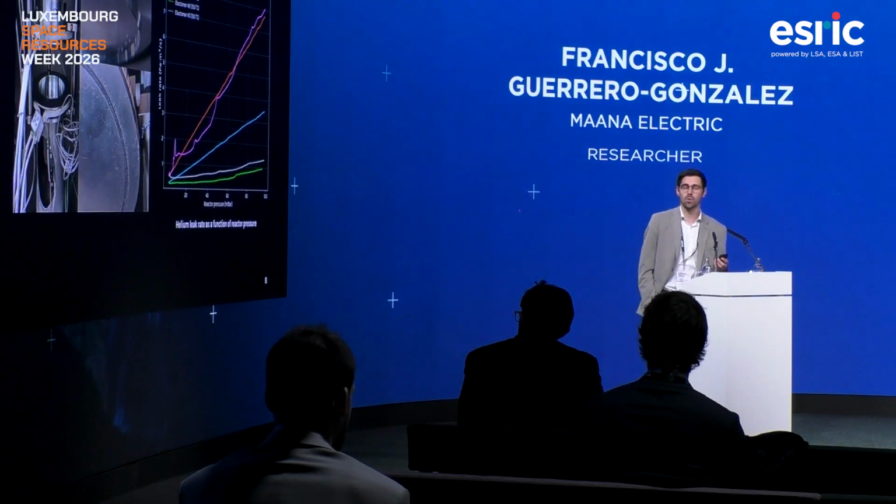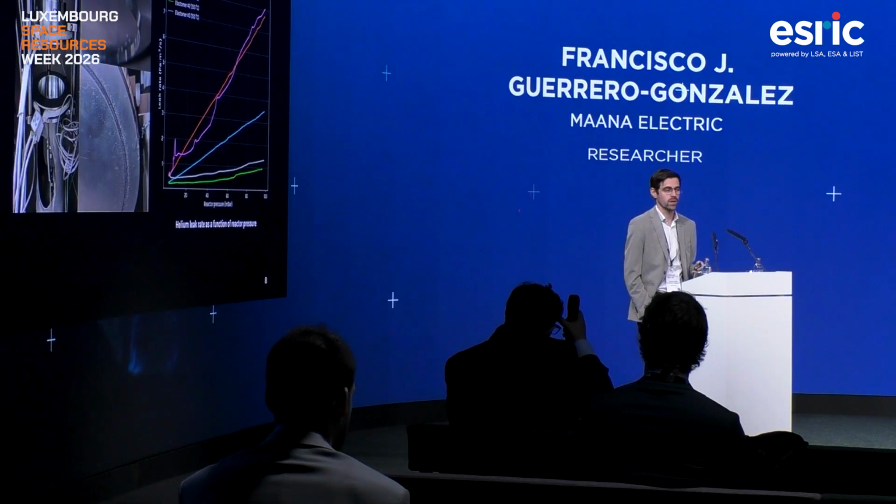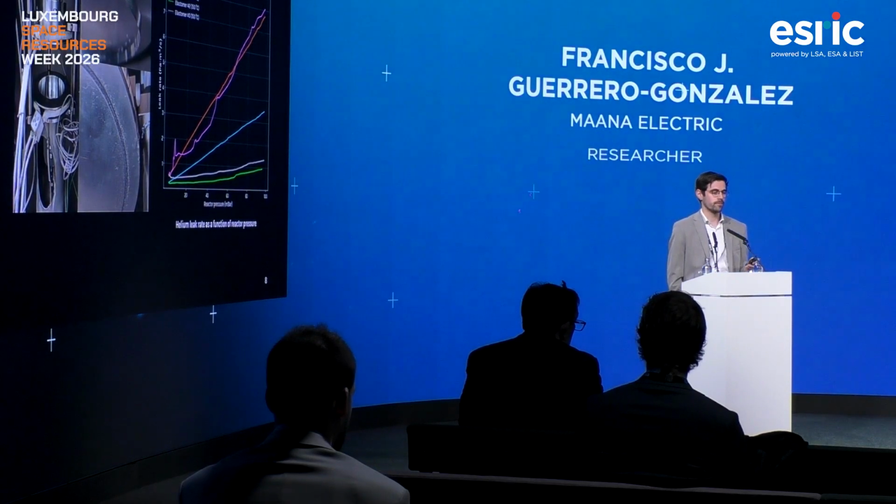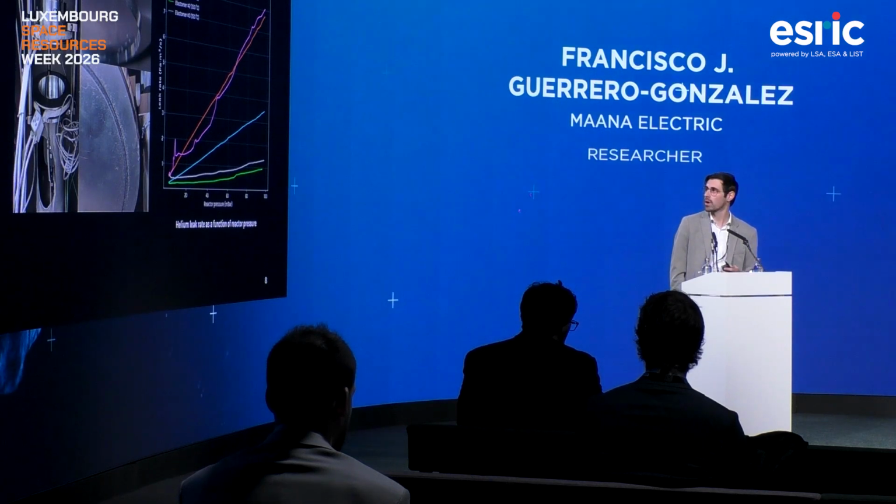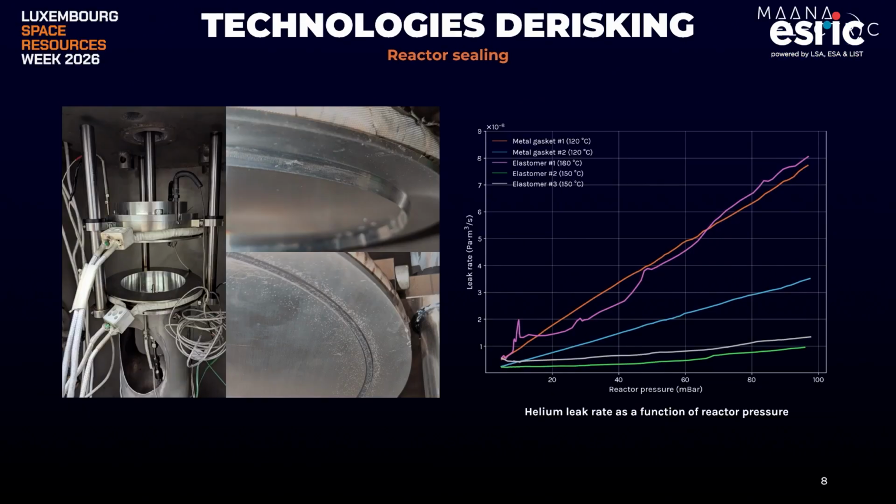The metal gaskets were a bit more tricky to work with because they have to be resettable. And in this case, that's why we are going to go for the future phases with elastomers that can work at higher temperatures and also provide a lower leak rate.